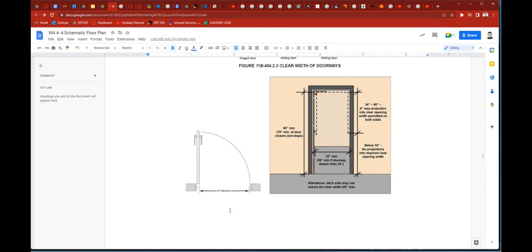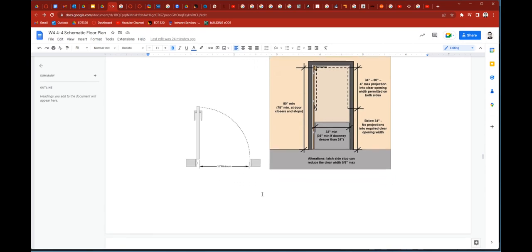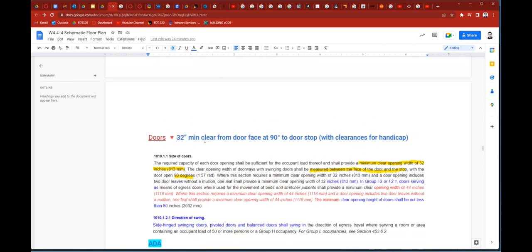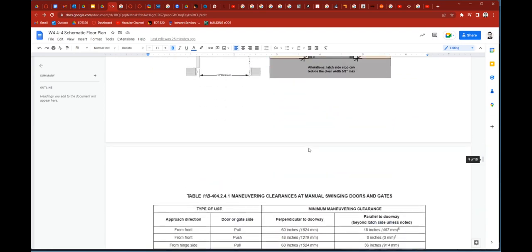that is used by the public and employees, because employees could also be disabled, and you can't refuse to hire them just because they're disabled, right? If they're capable of filling that position, then the facilities that will house your employees must be accessible to the disabled, and that's why architects use 36 inches. So although it says here a 32-inch minimum clear, they typically just use 36 inches.